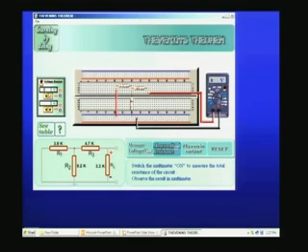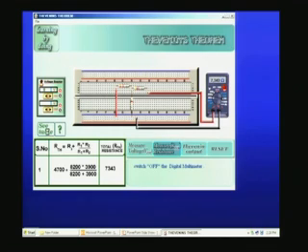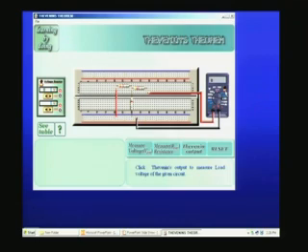So I will switch on the multimeter, to measure only the resistance. Immediately you can see it comes into resistance mode, and it measures about 7.343 kilo-ohms. So this is the Thevenin's equivalent resistance, and the calculation is shown here. R Thevenin is nothing but R3 plus R1 and R2 in parallel combination. So now we have measured both the Thevenin's resistance and Thevenin's voltage.